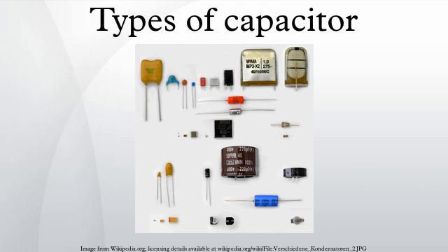The metallized construction makes it possible to produce wound capacitors with larger capacitance values in smaller cases than within film foil construction. Film foil capacitors, or metal foil capacitors, use two plastic films as the dielectric. Each film is covered with a thin metal foil, mostly aluminium, to form the electrodes. The advantage of this construction is the ease of connecting the metal foil electrodes, along with an excellent current pulse strength.